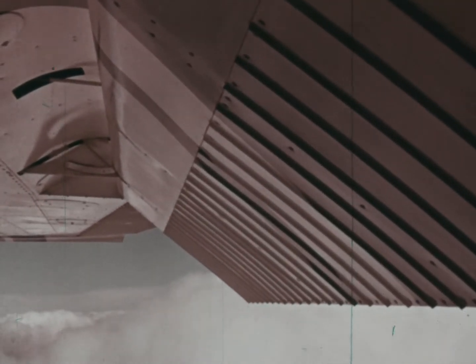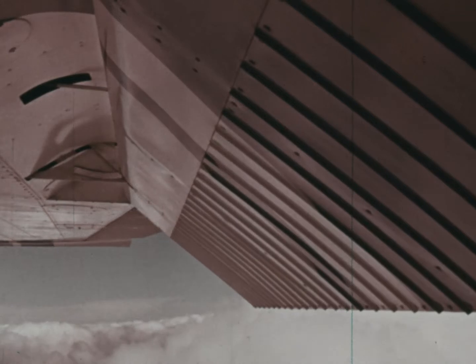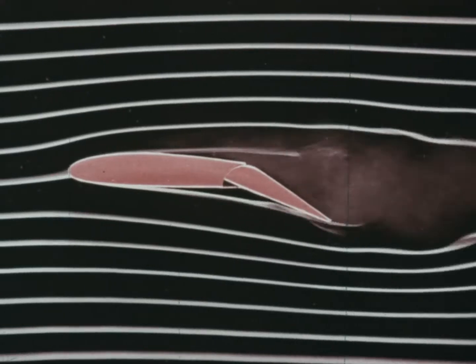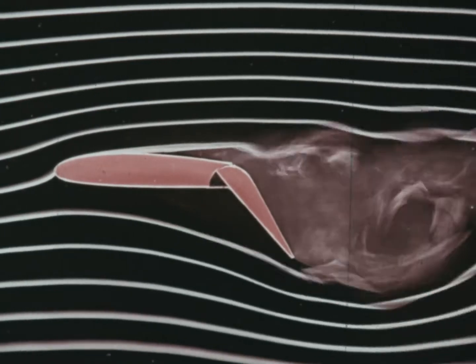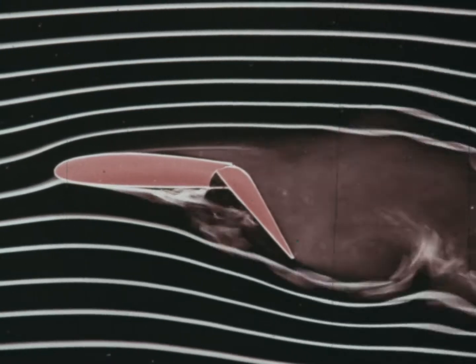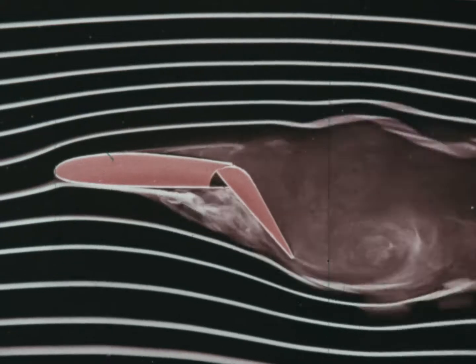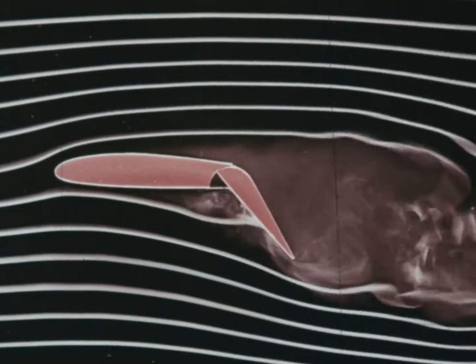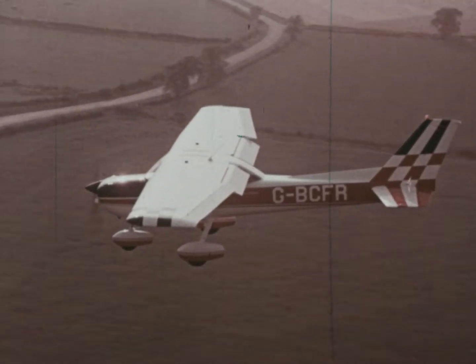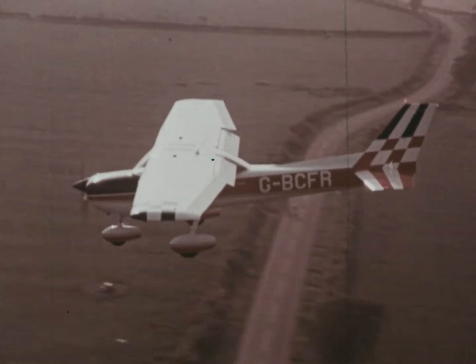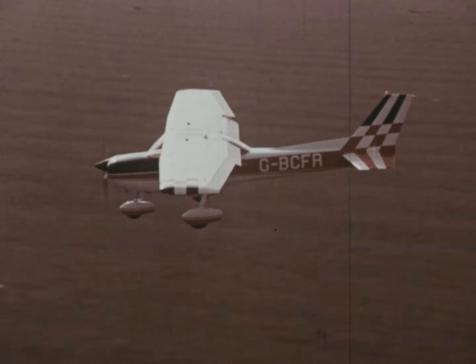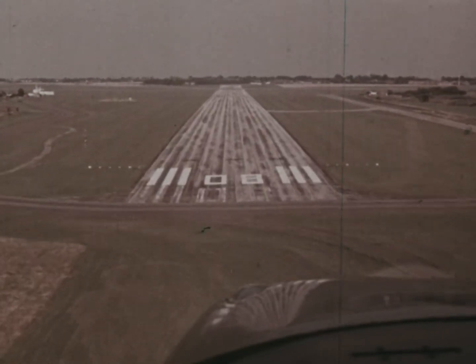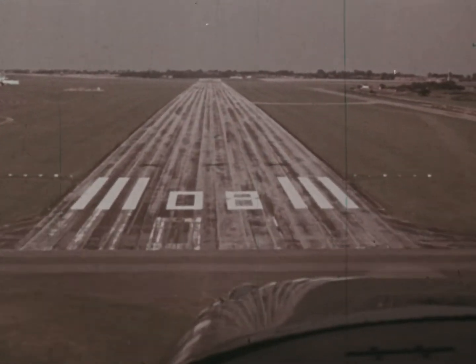With the flap fully deployed, lift is still maintained over the wing itself. But behind the flap, the airflow breaks up, slowing the airplane down by increasing another force acting on it, the force of drag. This enables us to approach the field at a steeper angle than we otherwise could, which gives the pilot a better view of the landing area as well as a lower landing speed.